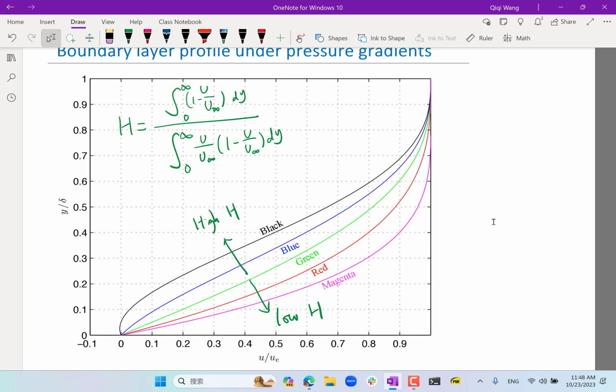If you look at this region where the flow starts to become negative in velocity, and imagine this boundary layer is subject to a continuous adverse pressure gradient, what are the forces if you just zoom into the layer of fluid that is becoming slightly negative or almost 0 velocity? What force is causing this layer of flow to move downstream?